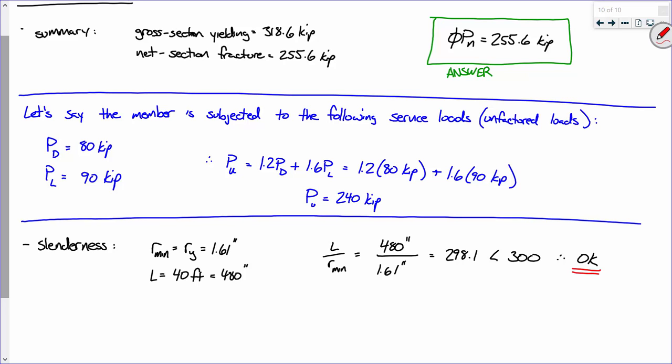But keep in mind, that's for a full-scale building. That's point 1. Point 2, RISA has built into it the shape database. All those shapes are in there. And it will do fundamental checks for you. But let's be clear. If you're just going to draw a bunch of lines on RISA and input some buttons and hit this little design check button and put the blinders on, and, as Obi-Wan did, put the blast shield over and just act on instinct, if you think that will work, it won't. You got to make sure that what RISA is doing makes sense. Okay?